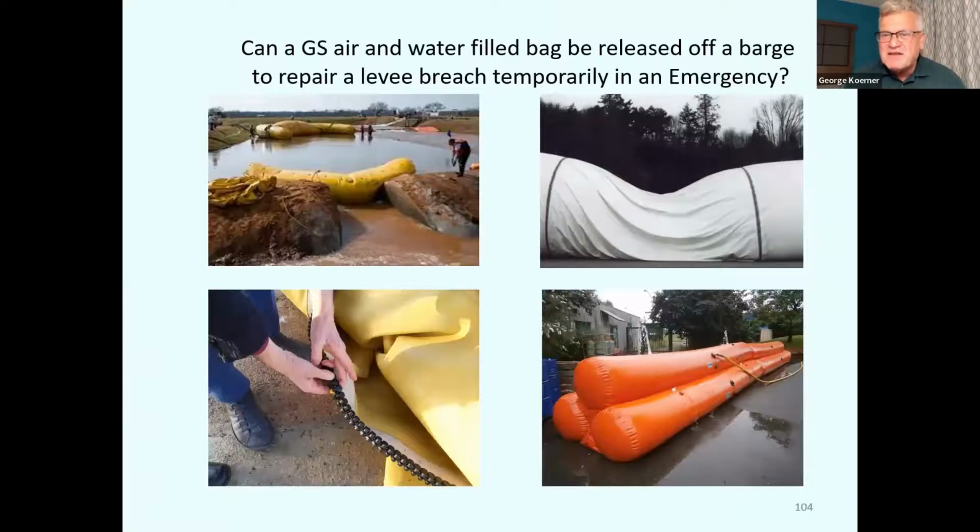Another big section of this is when a levee is breached, can you use a geosynthetic to block the levee so that you can basically put the finger in the dike, so to speak. This is done with geotextile tubes. The biggest finding from this is don't fill up the tube totally with water. Only fill it up in the neighborhood of 2/3 to 3/4 full. The rest of it will be open with air, and that subsequently works the best.